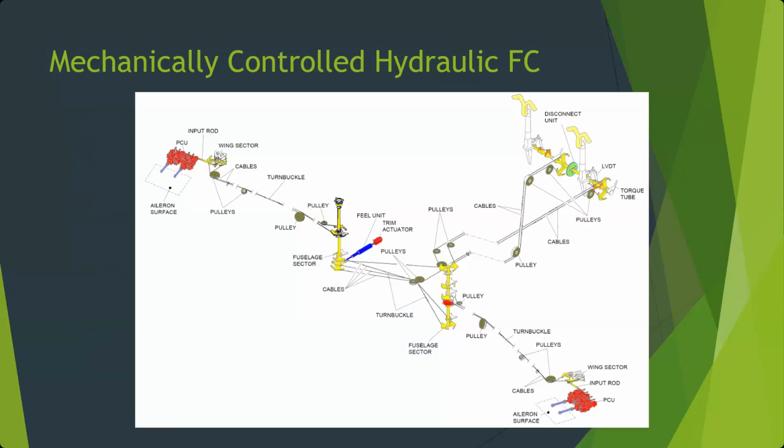But here's kind of that schematic of what this looks like. So here is a mechanical flight control system. This is looking at the ailerons. We have a pair of yokes up here. The yokes are tied together, and they're going to use these various cables to move what they call quadrants, or basically bell cranks. So cables come back from the flight deck into the wing box area between the landing gear, and then from here, cables go out to each set of what are called PCUs.